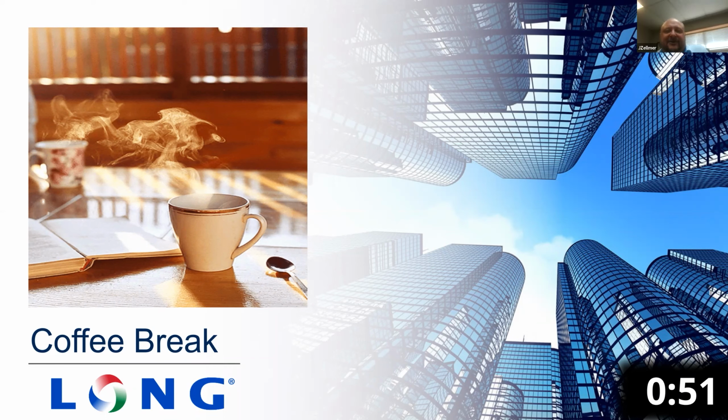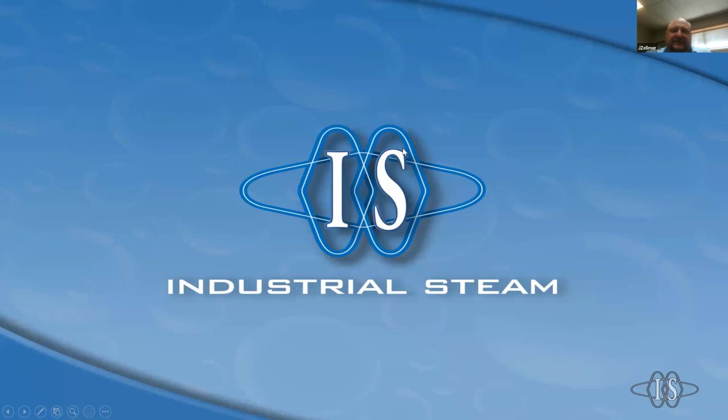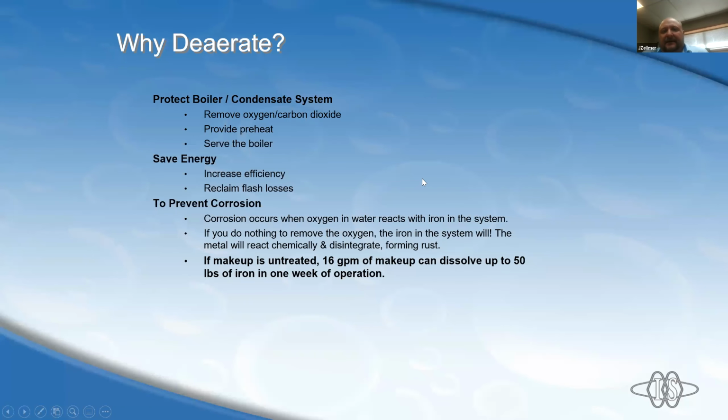Again, as he said, I'm Jeremy Zelmer with Industrial Steam. We make deaerators. Basically, we make any equipment that goes around all boilers in the boiler room. Today we're going to discuss why we deaerate. We are protecting the boiler condensate system. We're going to remove the oxygen and carbon dioxide, provide preheat, and serve the boiler. We're going to save energy by increasing efficiency, reclaim flash loss, and prevent corrosion.